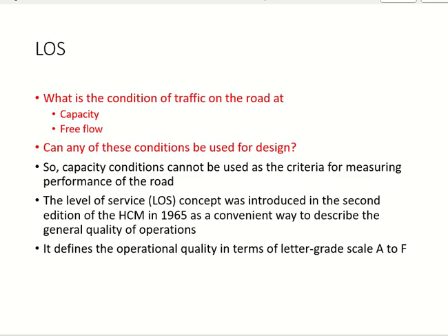So this is why the level of service concept has become very popular, because it gives you more levels than the extreme conditions. Free flow is an extreme condition, capacity is also an extreme condition, and after capacity you have failure, the traffic jam. So level of service gives you intermediate traffic conditions. It's basically a scale to measure traffic condition. And for your convenience, very easy to remember, the scale goes from A to F.